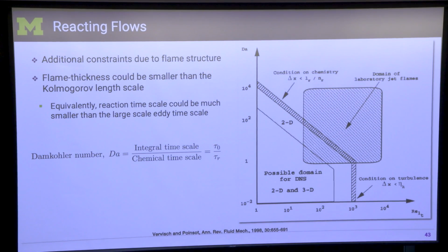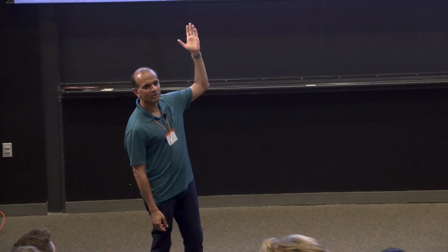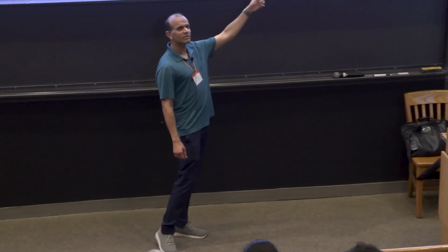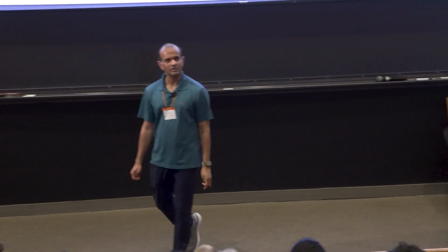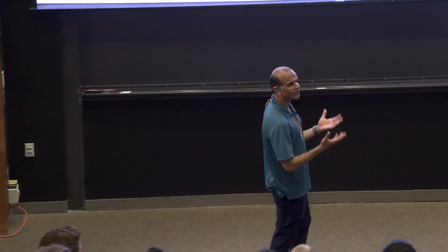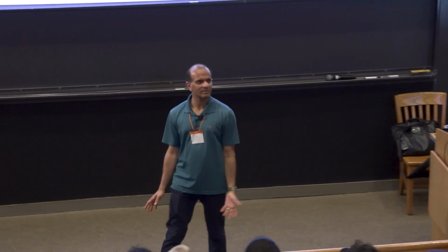Okay. So what you see is that you can simulate non-reacting flows. Damkohler numbers that are small or close to 0, you can go up to 1,000 on the scale. But the moment the Damkohler number becomes large, because you have to capture all those scales also, your grid has to become much finer, and then it starts going towards the other end. So if you keep increasing Damkohler number, the Reynolds number that you can cover also goes down. So this is important to remember. Whenever you see scalings like Reynolds cubed, that's only valid for non-reacting flows. For reacting flows, there's additional limitations from the chemical timescales.